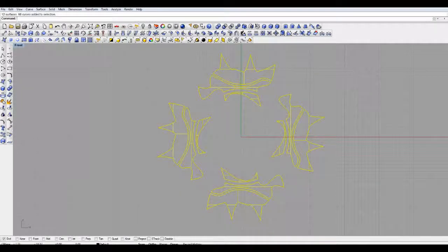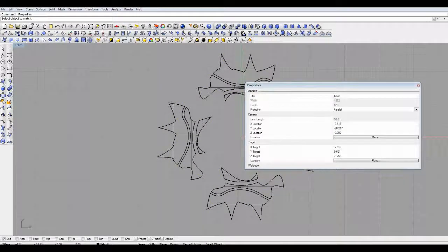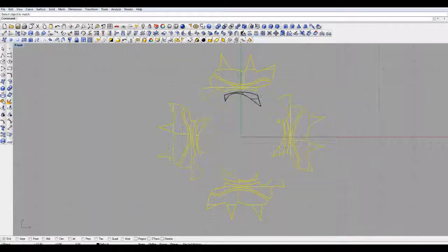Select everything, go back, hit Match, hit OK. You select the brown surface. And you'll see the selection menu come up if you selected something that multiple objects are lying on top of. It'll ask you to pick which one you want if it detects multiple things that are intersecting. So you want the surface that's brown. And now, close this out, after using Match, it has applied that color to everything. Very handy. Turn that off.